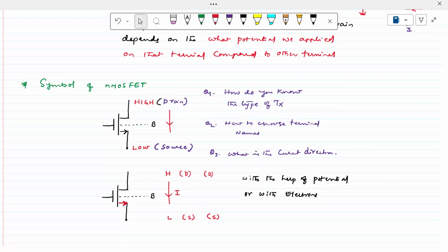So this is very important. Finding the source and drain of a MOS transistor is very important when we are analyzing analog circuits. If I ask you about a particular analog circuit, you should be in a position to say what the potentials are at the particular nodes, and depending upon the node potentials, say the current direction for NMOS as well as PMOS. That is the reason why we discussed this.